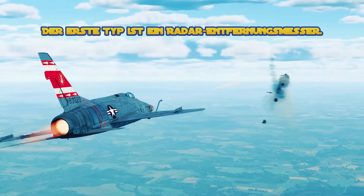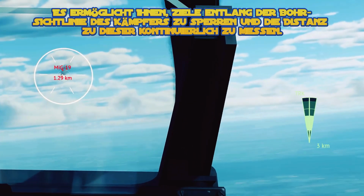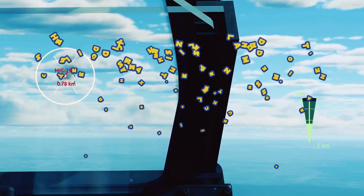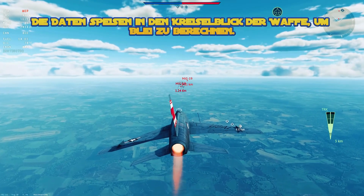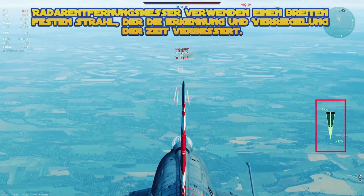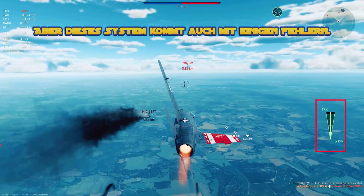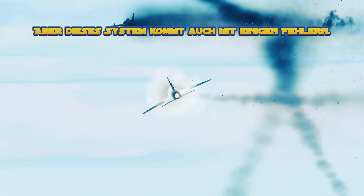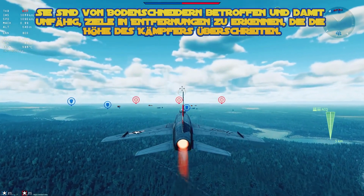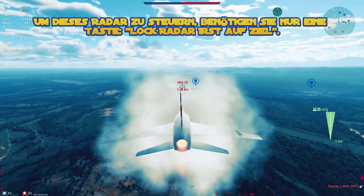The first type is a radar rangefinder. It allows you to lock on targets along a fighter's bore sight line and continuously measure the distance to it. The data feeds into the gun's gyro sight to calculate lead. Radar rangefinders use a wide fixed beam, which improves detection and lock-on time. But this system comes with some flaws as well. They're affected by ground clutter and thus incapable of detecting targets at distances exceeding the fighter's altitude.